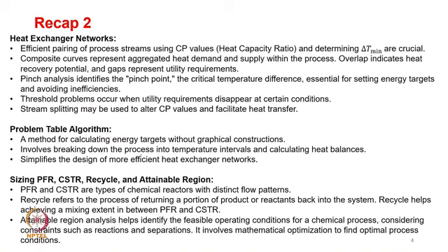Then we also spoke about how to size reactors. Basically, the geometric way of sizing reactors, wherein we talked about plug flow reactor, CSTR, recycle, and also looked at a concept known as attainable region. Identification of the attainable region typically helps in obtaining the feasible operating conditions, considering the constraints and other